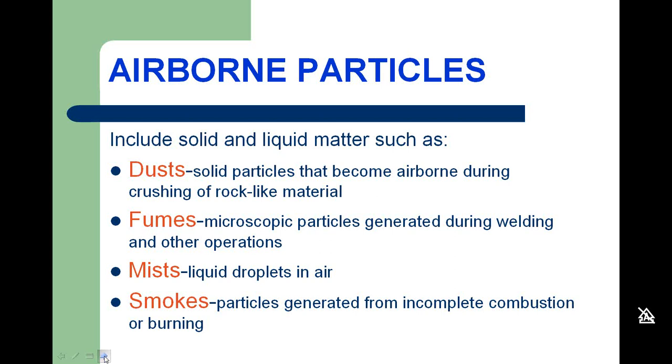Fumes are microscopic particles generated during welding and similar operations. Despite what we hear every winter on TV news reports, people are not overcome with carbon monoxide fumes. Carbon monoxide is a gas. Mists are liquid droplets, and smokes are particles generated from incomplete combustion.